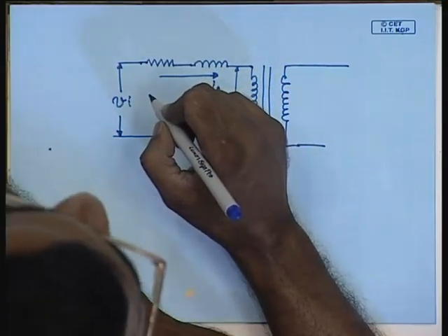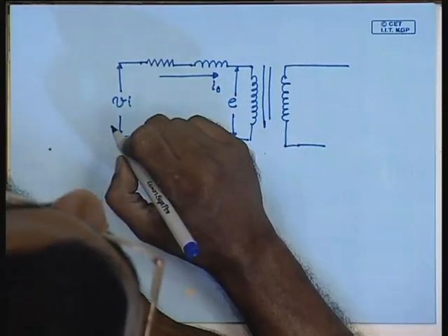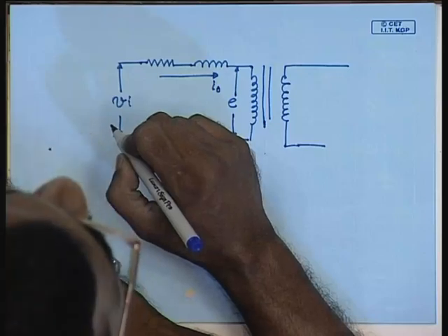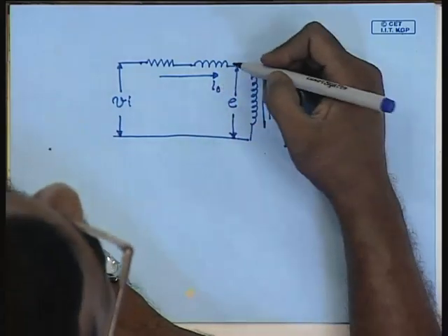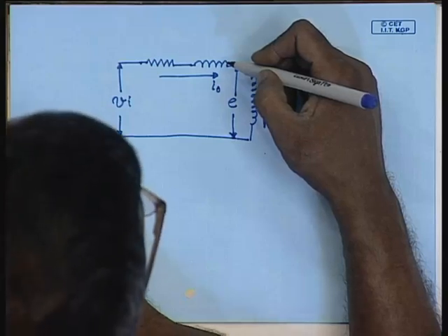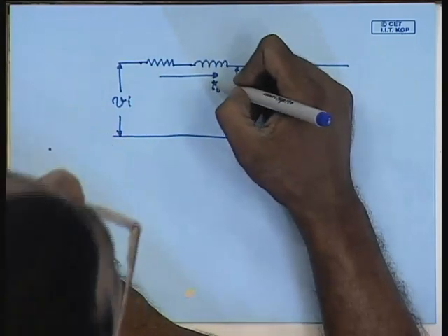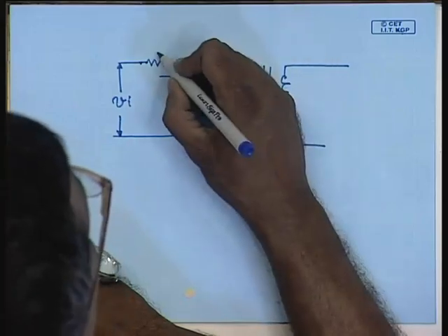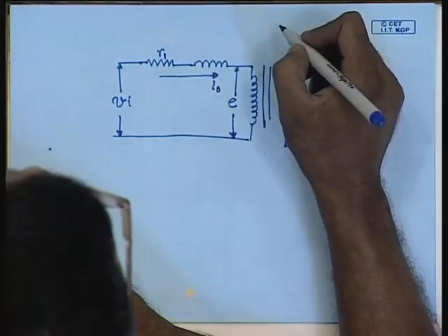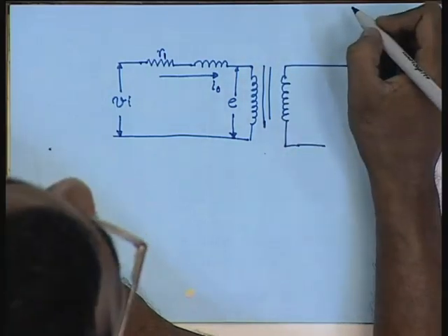Hence, even the flux waveform will possibly not be exactly a sine wave, which may or may not increase the harmonics in I0 depending on the nature of the BH characteristics. However, since I0 magnitude is very small and also the stator resistance is small, E and phi m can for all practical purpose be assumed to be sine wave.